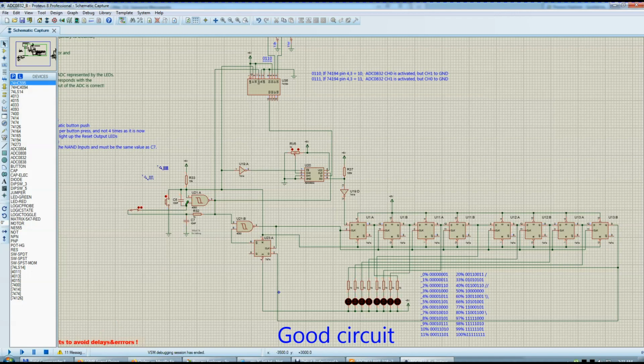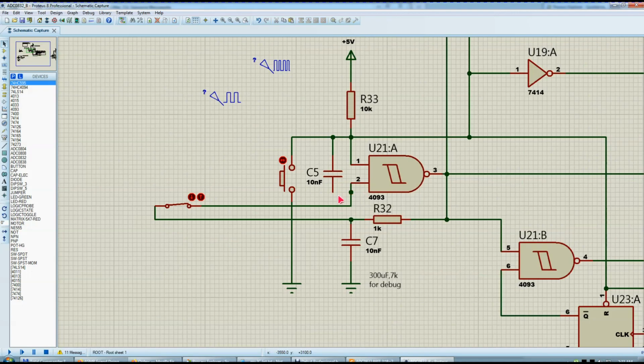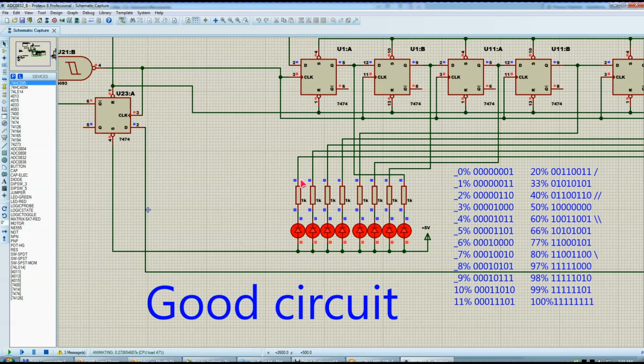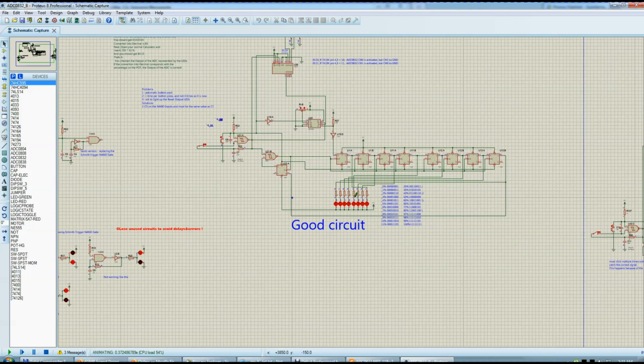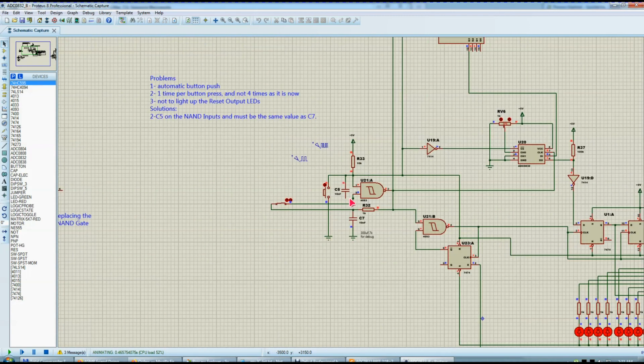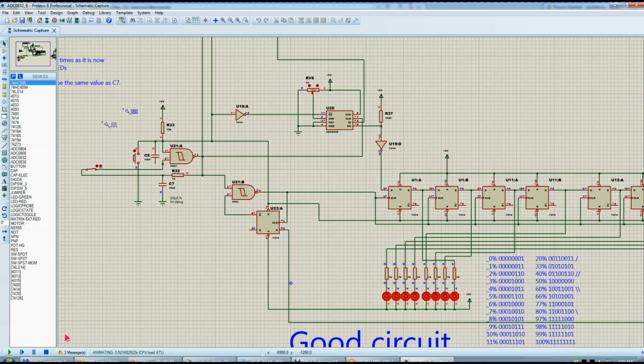Oh, I believe I know. I think I know. Let me take out that capacitor link from there, and this should give us... Yeah, there it is. There is the error, and everything is on. You see, actually everything is off, it is negative here, and it is permitting these LEDs to stay on all the time. So that capacitor is actually helping a ton for correctly transmitting every time I click once.